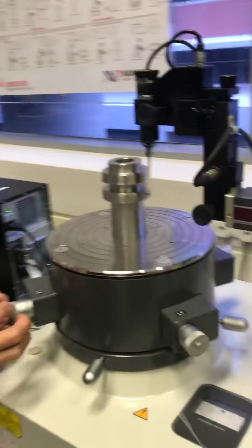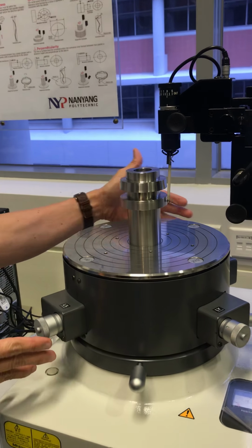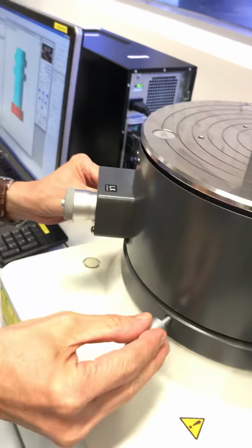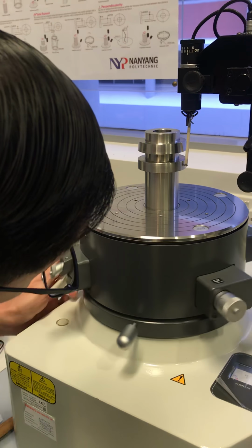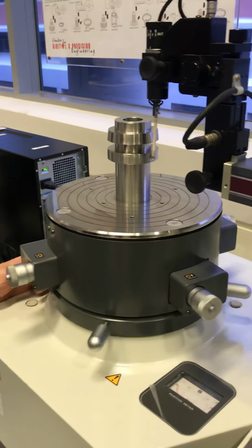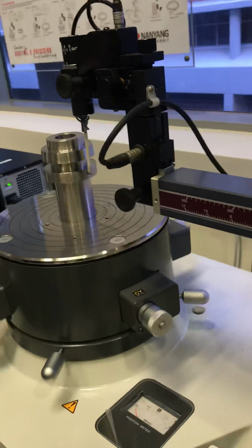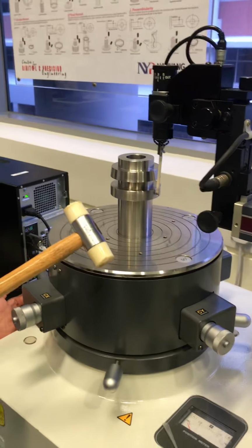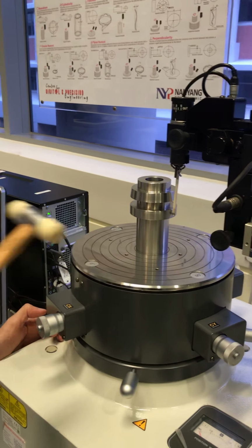So there's this dial here for moving the X and Y. Please don't rotate this. This is a motor. Don't put your hand here. Put your hand here. This is a handle. Am I clear? Yeah. Then observe the gap. Equal or not? Yeah, it's very equal. If it's not equal, then you use this mallet to tap. Tap this side, not this way. Tap this way, you will hit the probe and then your sensor. So always tap away. At the smallest gap, you just tap away.